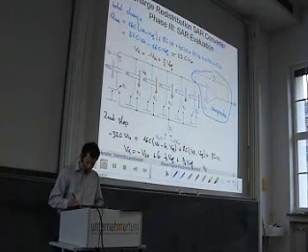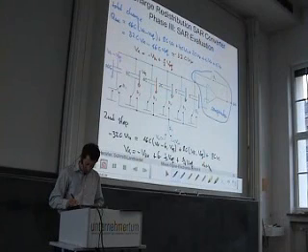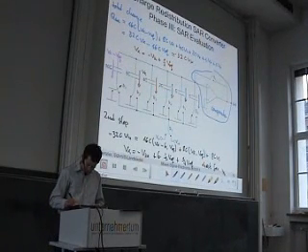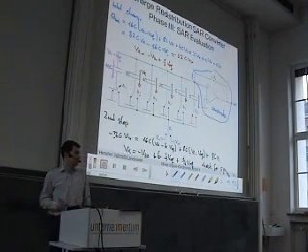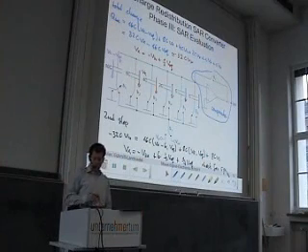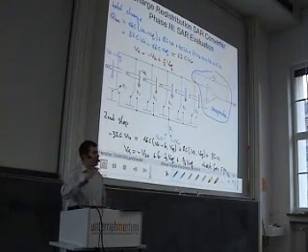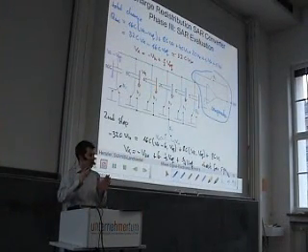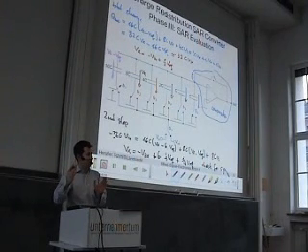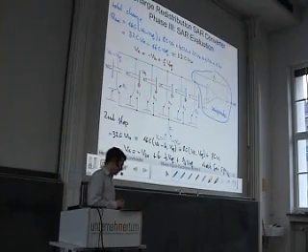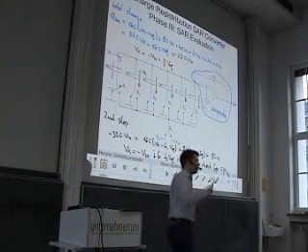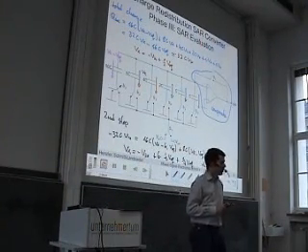So this is the next step, and here we have to check again for the sign. And so on and so on. The increment is always reduced. We add it, we increment it by toggling the switch, we check the sign. Depending on the result, we keep the switch position or we switch it back. Okay, there was a question.